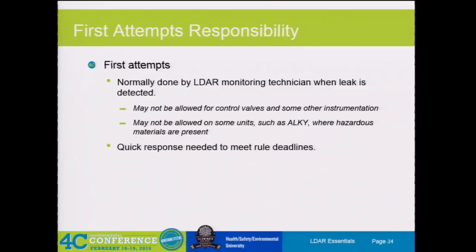What I was going to say is we talked about it earlier. There's out of service, then there's LDAR out of service. Is that pump purged? Did somebody come in and blow nitrogen through that pump to clean it out when they shut down pump B? I highly doubt it. It's still got process in it. It's still in LDAR service. So like he said, monitor it in whatever state you find it in, unless it is purged, then don't. If it is purged, then take it out.